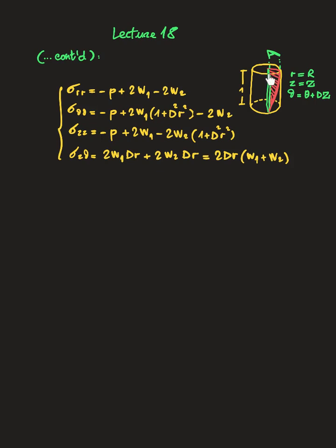The rotation is given by dz, but since the height z is equal to 1, this angle is measured by d. So this is the experiment that I'm doing, and I'm trying to compute all the forces that build up in the cylinder when applying this torsion. This d is measuring the amount of twist that you are prescribing on the cylinder.